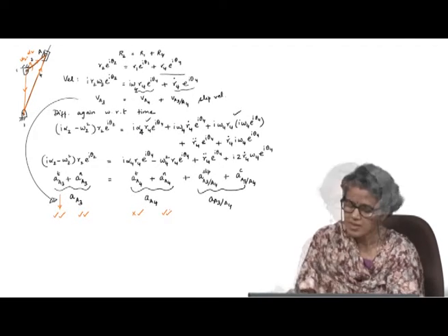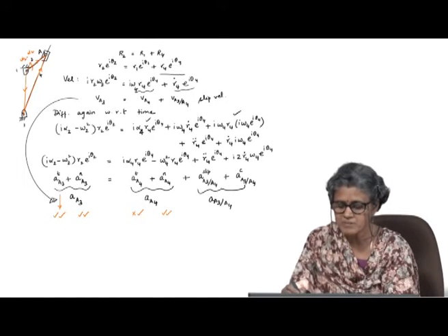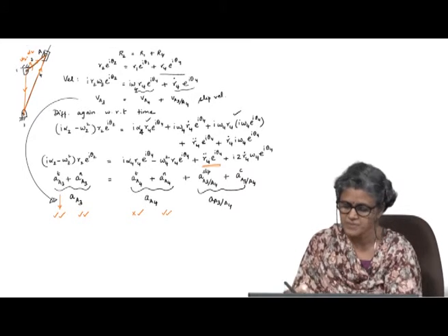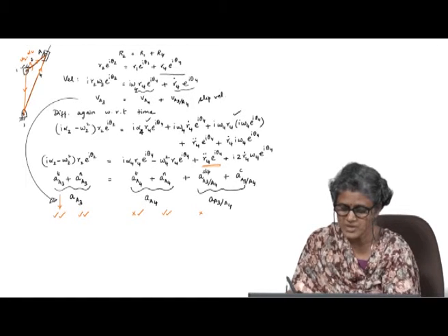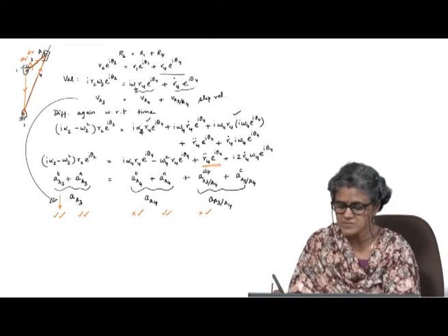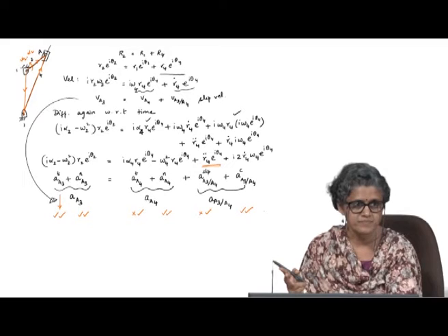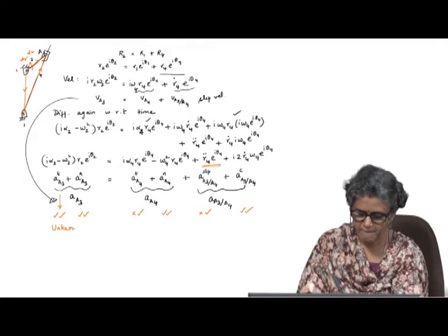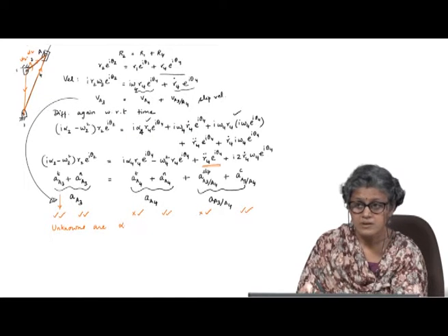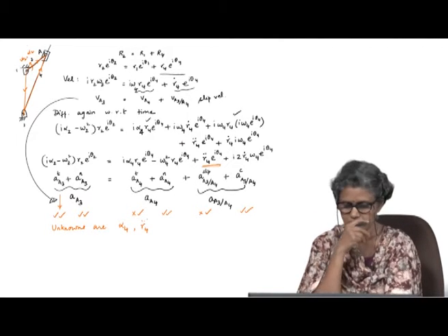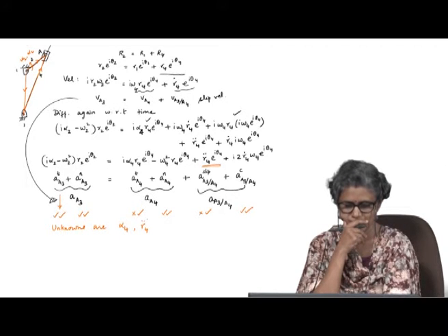Normal component completely known. In this case the slip component, what do I know about it? If I look at this term here, I know the direction, it is along the link, but I do not know the magnitude of R4 double dot. So, here R4 double dot is unknown, but I know the direction for this term, and for the Coriolis term again it is completely known because of the velocity analysis. Again 6 terms, 2 unknowns. What are the 2 unknowns? Alpha 4 and the slip acceleration R4 double dot. Those are the 2 unknowns, and you can solve for them either analytically or graphically.